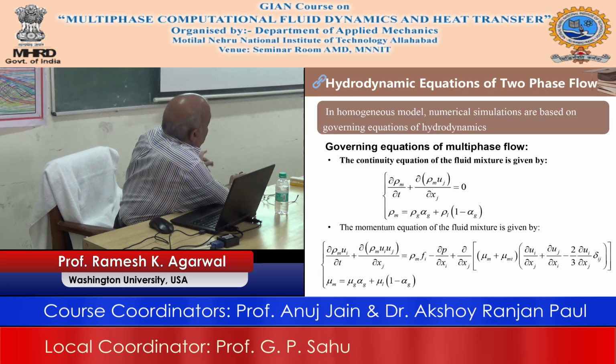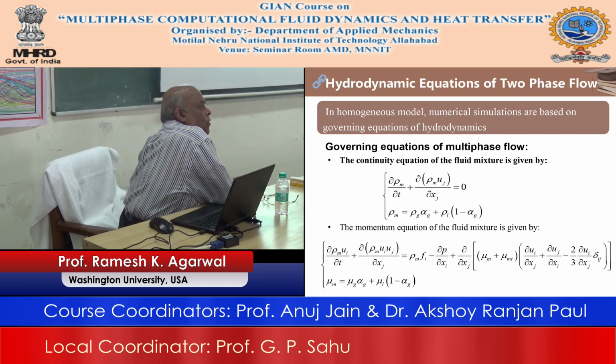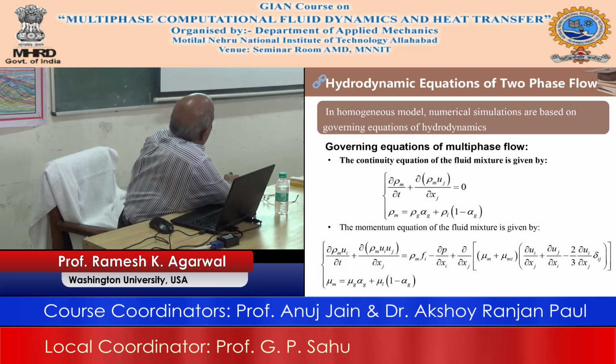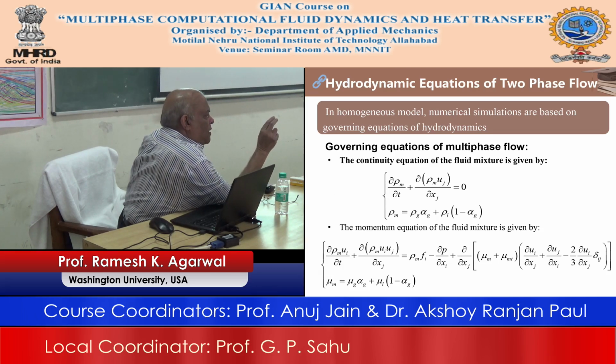Also in this case, we are only going to use one equation. So it is not a two fluid model. It is a single fluid mixture model, the simplest one. So what you have is a mixture, M denotes the mixture, and the density. It is more like the formulation that we had for a nanofluid. In the case of a nanofluid, the difference was that we had a solid nanoparticle. In this case, we have the liquid and air.